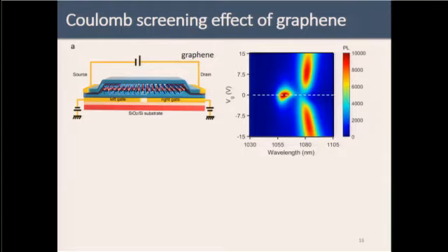So in our device, we actually use graphene as source-drain electrodes. That means part of our molybdenum telluride is covered by this few-layer graphene. Why do I mention that? Because when we shine a light, we can choose the region where we shine. We can shine in the area that has graphene, and we can also choose to shine in an area that does not have graphene. What could we observe? From this gate-dependent measurement, we select the charge neutrality,